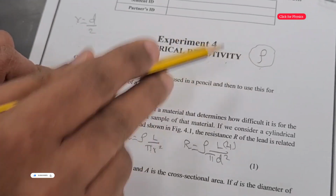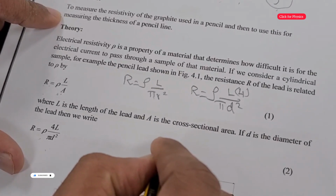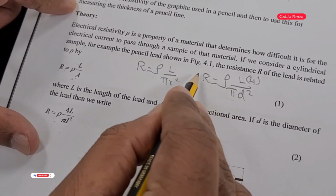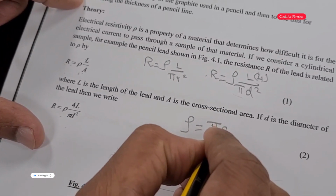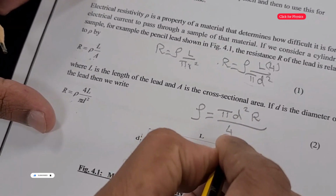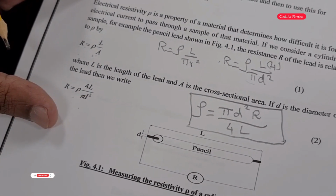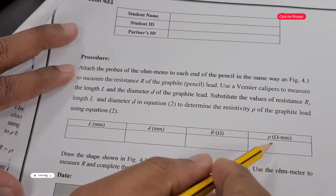Now, what is our objective? We are going to find the resistivity. So rearrange this equation. If you rearrange, rho is equal to pi d squared, which comes to the numerator, multiplied by R, divided by 4L. This is our equation for our first table. So what is our first table? Our first table is given here. We are going to use that formula here.